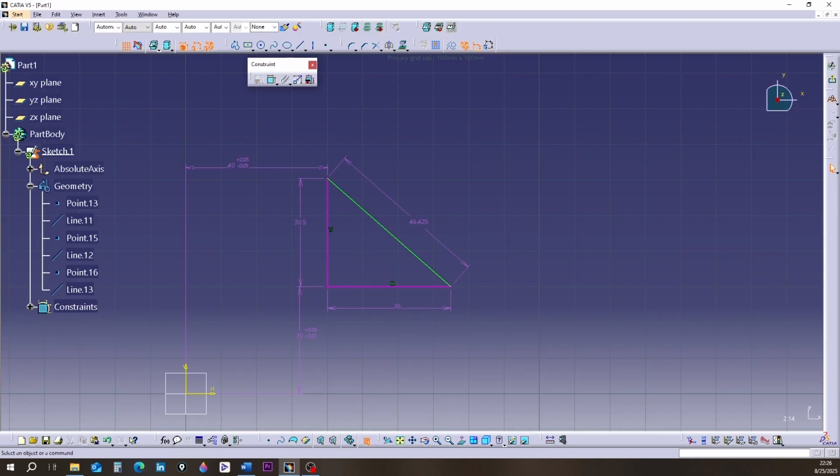Here I have given an extra dimension on the internal dimension of the triangle. I don't necessarily have to delete exactly this dimension. I will delete one of the other dimensions related to the triangle's side. I click on one of them until it turns orange. I press the Delete key on the keyboard. It is seen that the triangle turns green again.